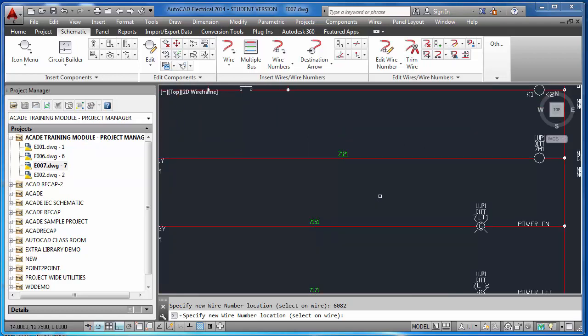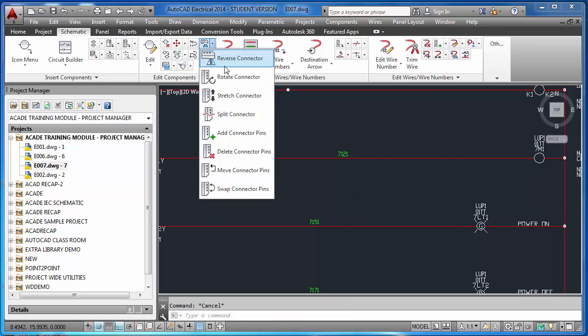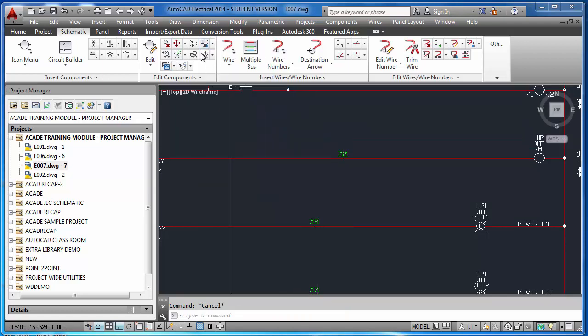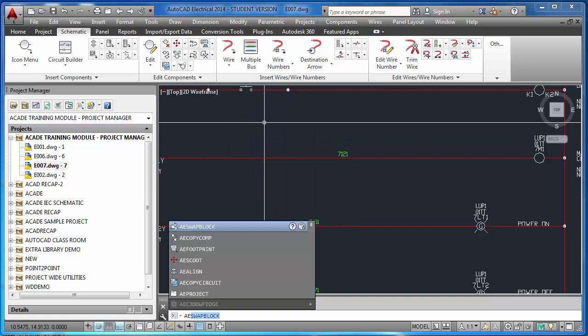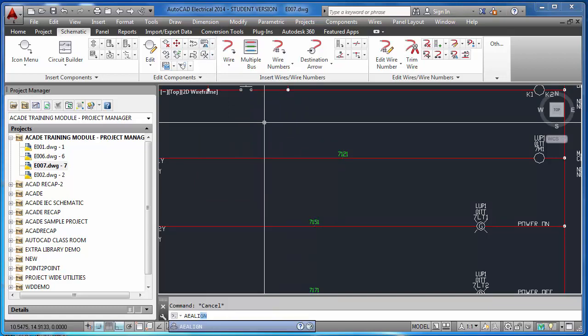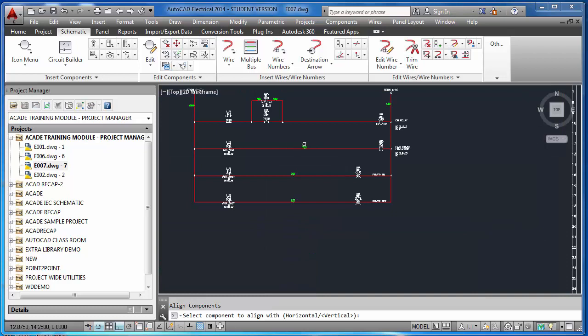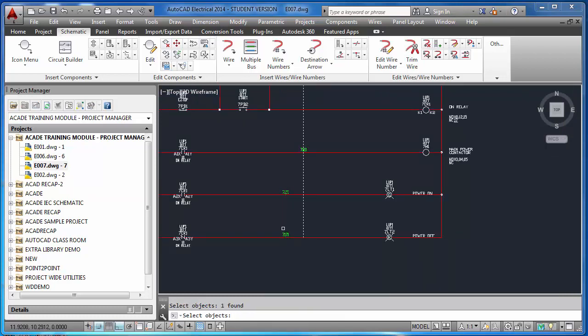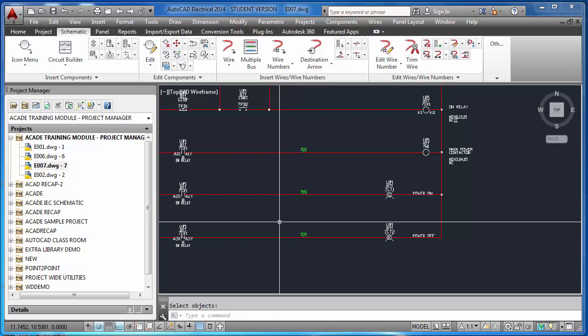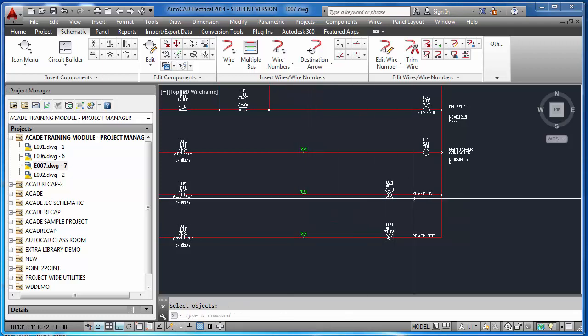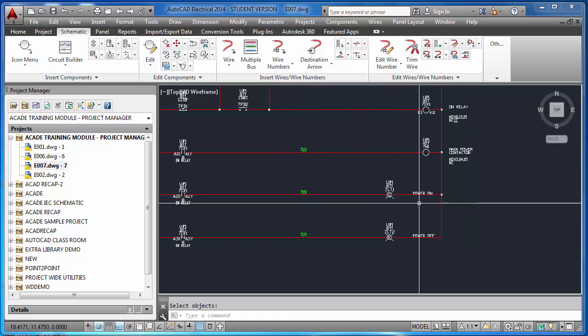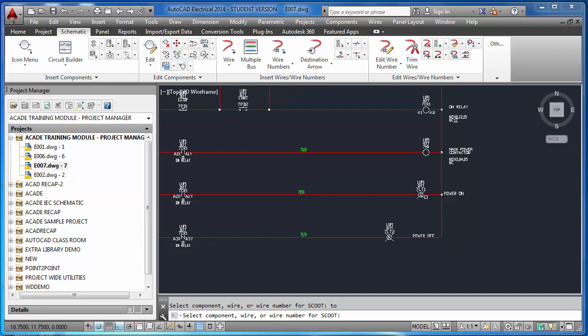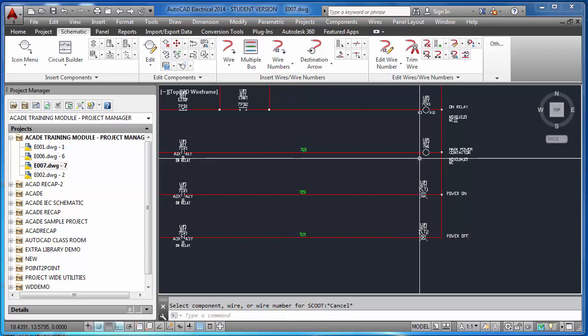And align, we have learned about using the command align. Even in AutoCAD Electrical you can use AE align. Select the first one, and it will come like this. So bring everything on a line, and if we want to move this a little bit here and there, you can do this, or even you can use align for this.